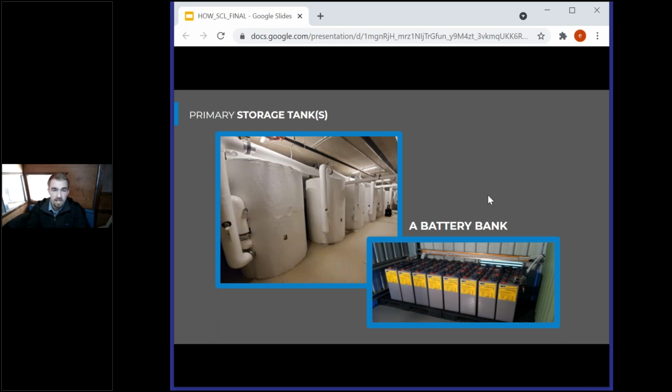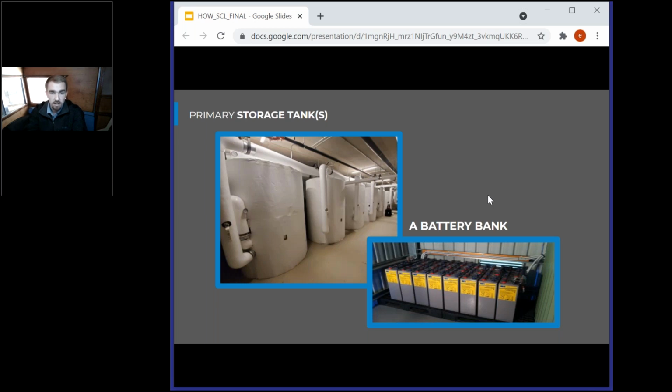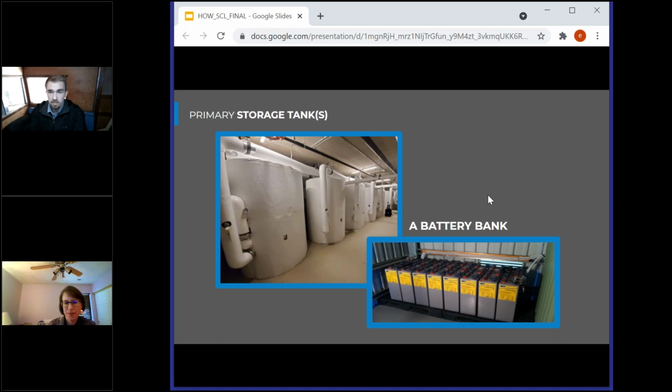And then your heat pump's acting like a trickle charger, just recharging that storage throughout the day. So anytime there's a big peak, the storage can send as much hot water out as it needs, while the heat pump just slowly recharges that. And that also allows the heat pump to run for a much longer period, which is a lot easier on heat pumps, because the longer they run, the more efficiently and reliably they can run, because they've settled into this heating cycle, and it's a lot harder for it if it turns on and off really frequently.